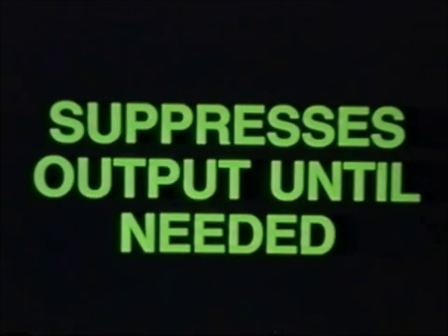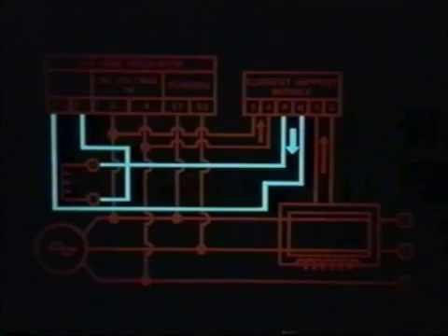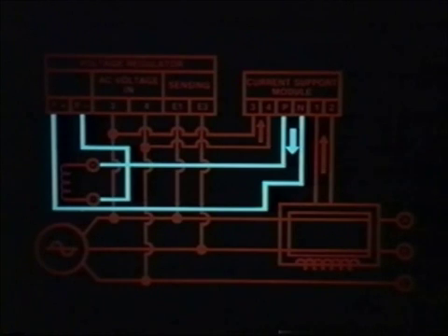Although manufacturers of these systems have different schemes to initiate and control output DC current, the basic design usually incorporates a form of voltage comparator circuit to suppress output to the exciter field until the main alternator's voltage is depressed to a preset level. Once that level is reached, the controller will allow controlled DC power to flow directly to the exciter field.